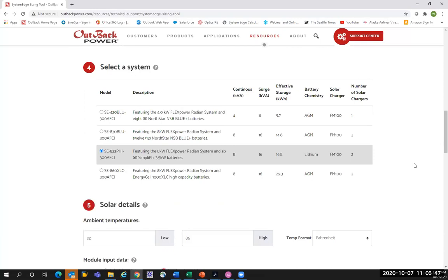I said, look, even before I found that out, I can tell just by the way this thing's struggling to start. I've worked with motors a lot. I said, you're going to need to put a variable frequency drive or a soft start on this motor, which they did ultimately.